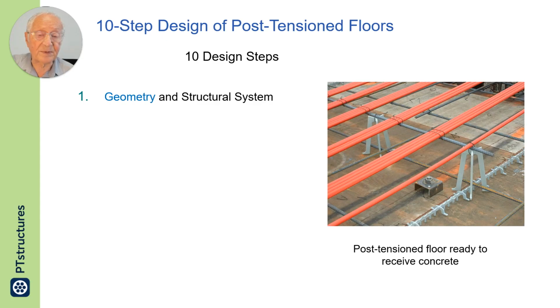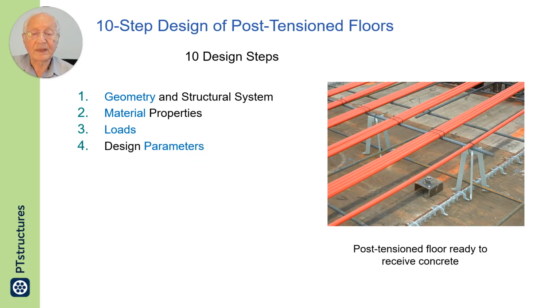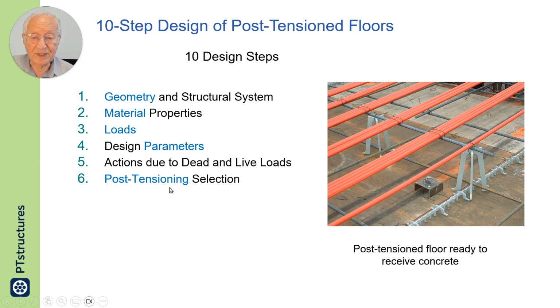We follow 10 steps. Step number 1 is geometry and structural system definition. Then we define member properties. I am going through the optimal sequence of design. Then loads. Define design parameters. Then we calculate the actions, moments, and shears due to dead and live loads. We select post-tensioning.